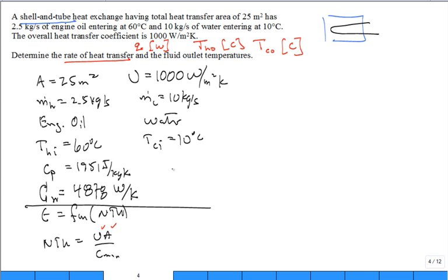All right, get the specific heat of water, about 4190 joules per kilogram degree C. I have to assess, well, what temperature is it going to come out? Maybe it comes out at, I don't know, 30 degrees or 20 degrees. So if I assume that it has an outlet temperature, a little over 10, then I just get the specific heat.